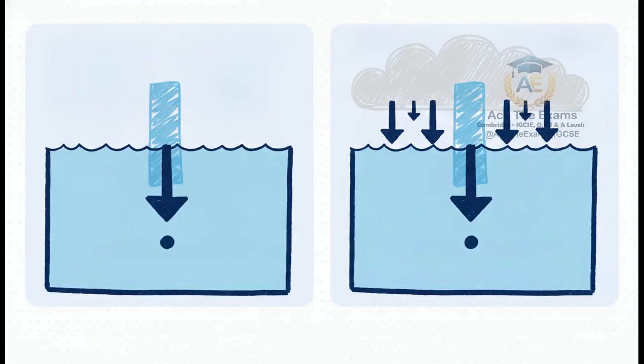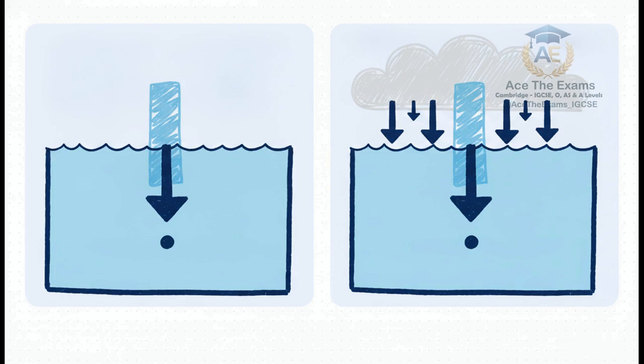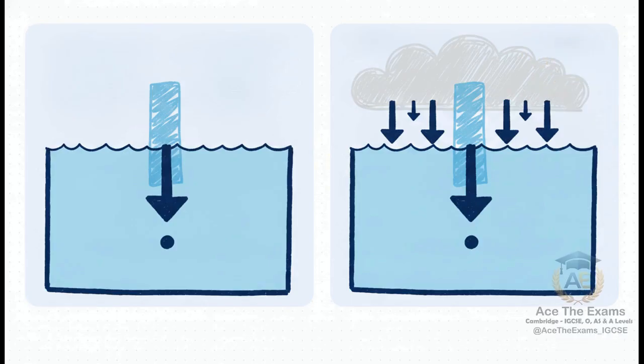All right, stepping up the complexity a bit, let's talk about pressure inside a fluid. When you're looking at a point, let's say at a depth h below the surface, the pressure is caused by the literal weight of the liquid column directly above it. That gives us our first major equation. Pressure P equals rho times g times h. Rho is liquid density, g is gravity, h is depth.